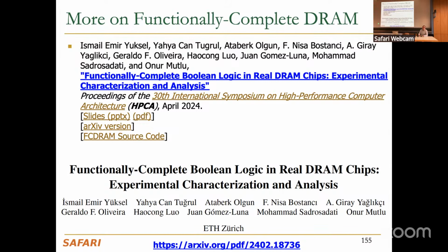Oh, okay. So for example, the manufacturer may ignore an activate command that comes too close after a previous activate command, right? That's very easy, actually. They just need to add additional circuitry to ensure that another activate doesn't happen while an activate is in progress, right? Exactly, yeah. Some manufacturers do that. I don't think it's necessary for them to do that because, in my opinion, it limits the capability of their chips, right? Because they're not liable. They basically say, don't use the chips this way. It's already said that way. Why add another circuitry to prevent that, right?